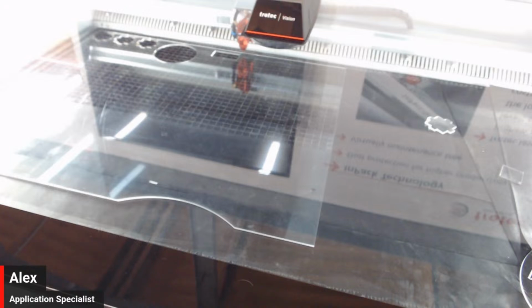And another thing just to note, a common thing I see, is people tend to always increase the resolution here if they need a more detailed engraving, but it doesn't actually always work like that. What it means is that your laser is overlapping a lot. So if you go to 1000 and you don't have the right lens or the right type of laser technology, then your laser is overlapping a lot and you're actually losing definition because it's kind of firing twice in the same place to get the same effect, which is why, for example, you'll often find if you're doing detailed imagery in wood, it's better at 333 versus 500.